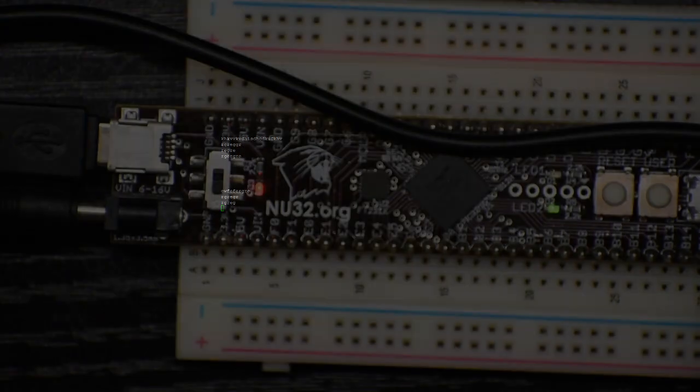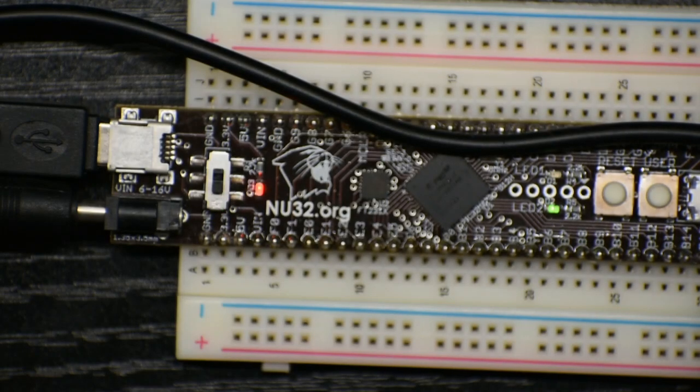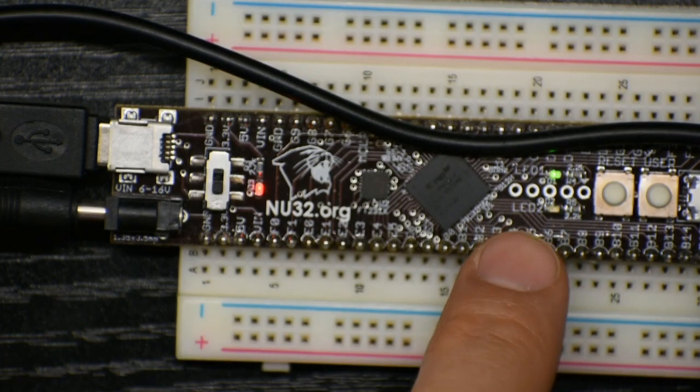This particular program, Talking PIC, and we'll review that in the next video, says if I ever receive any data and then the enter key, I will send it back. So if I mash my keyboard, all these letters are being sent to the PIC, but the PIC doesn't respond until I hit enter. And when it does, it sends all those characters back. So I can type stuff and enter and stuff and enter. You could hit enter a bunch of times and blank lines get sent back. And you'll notice that the LEDs are programmed to invert every time we hit enter. So each time I hit enter, we see the LEDs flick back and forth.